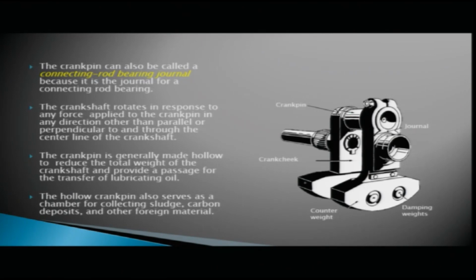The crank pin is generally made hollow. It is made hollow to reduce the total weight of the crankshaft and to provide a passage for the transfer of lubricating oil. The hollow crank pin also serves as a chamber for collecting sludge, carbon deposits and other foreign material.